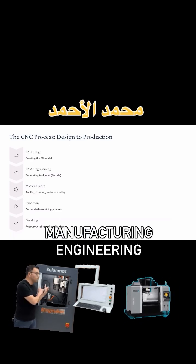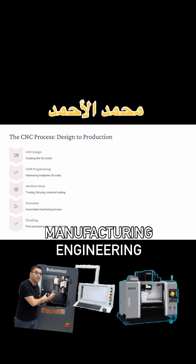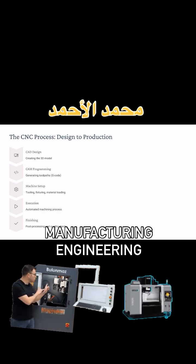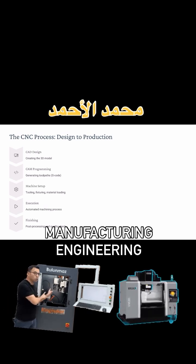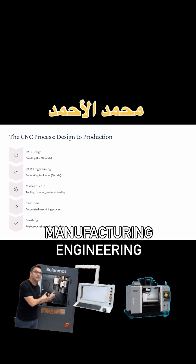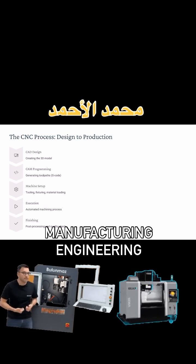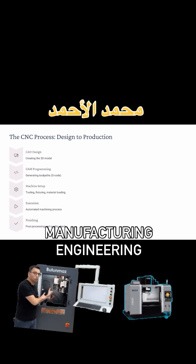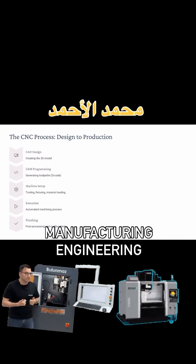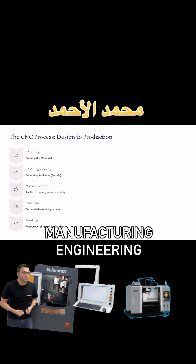As you can see, CNC machining follows a clear workflow. First, we use CAD software to design the 3D model. We've been taught SolidWorks here in our college. You can use other software as well. One of the most famous ones is Fusion 360. After that, we use a CAM, which will generate our G-code from the model we have. After that, we just set up the machine with the tools and materials, and then we run the program, and the machine just starts cutting the parts miraculously. Finally, we check and finish the part of the product. Is it finished? Is the finish to our liking? If it is, then we just move to other processes.